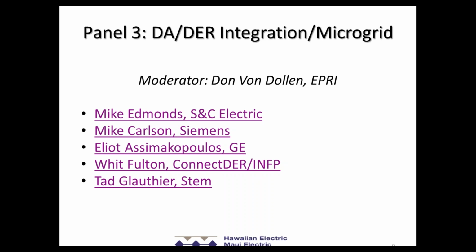With the fault level reduction, there's also a frequency impact. As we just talked about the fault levels, now you're going to have a less stable grid from a frequency standpoint. So that really opens up a market for storage; it's well known, well documented. But there are twofold issues to deal with from a technical standpoint. I think it's both. I don't think you're going to be able to replace the fault level because there's just so much to replace. It's going to be a combination: anticipating the changes, which your planners can do, and starting to reinforce the grid so we can add those in there, but also thinking about the role for other services that DERs can play to actually increase that.